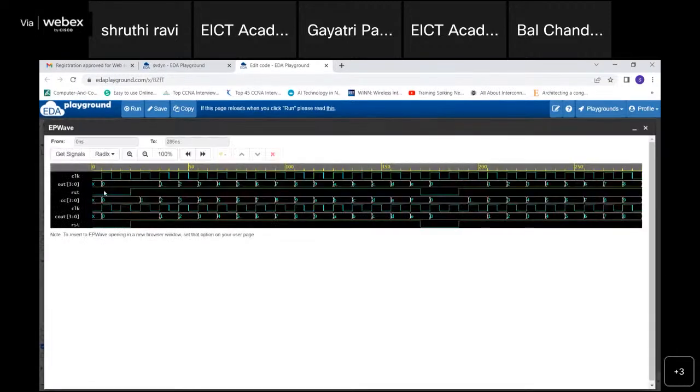So we can clearly observe that the intermediate register takes the value at the right time as per the changes, but when it is moving out on the clock to the output register, it is taking one clock delay. This output here is with respect to the test bench, and this C out is with respect to the DUT, device under test. So we compare this with the register that we have used intermediately to do the operation and storage. So we have a delay of one clock cycle.